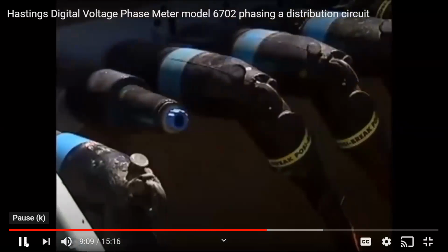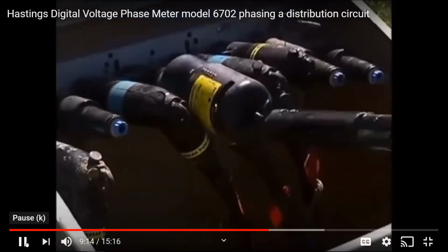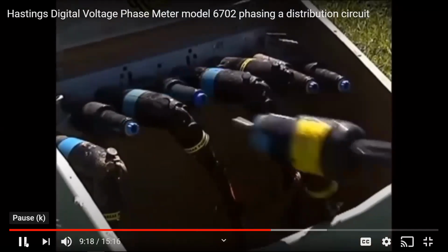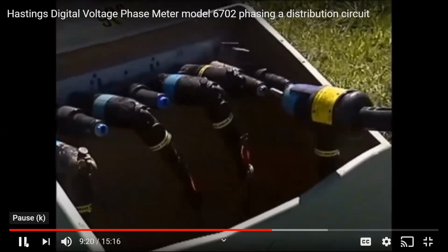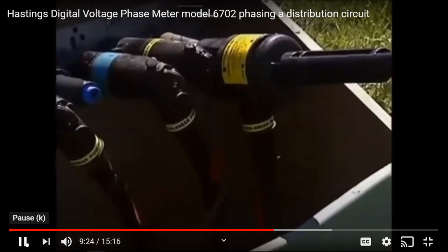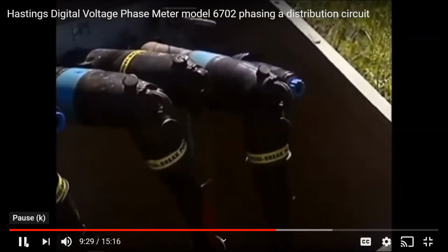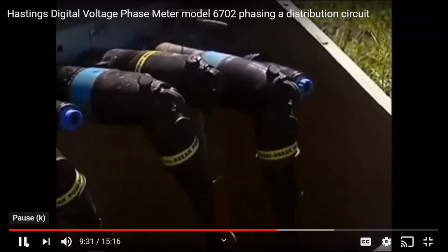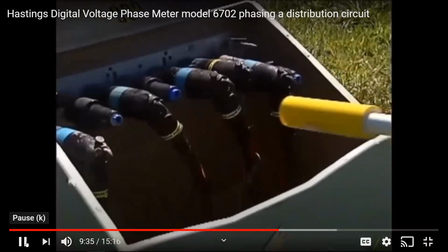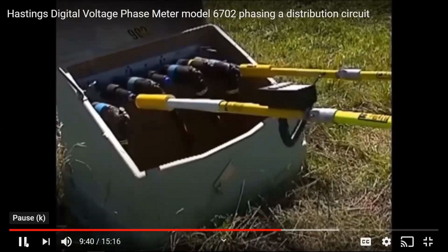Okay, Kirk, we've tested that first cable and found it to be fully faulted. Let's take another cable of your choice and put in that feed through, and we'll check the condition of that cable. Hopefully we'll have a good cable. We can get some of these consumers back on. You got the metered end. I have the non-metered end. I'll plug into that feed through.